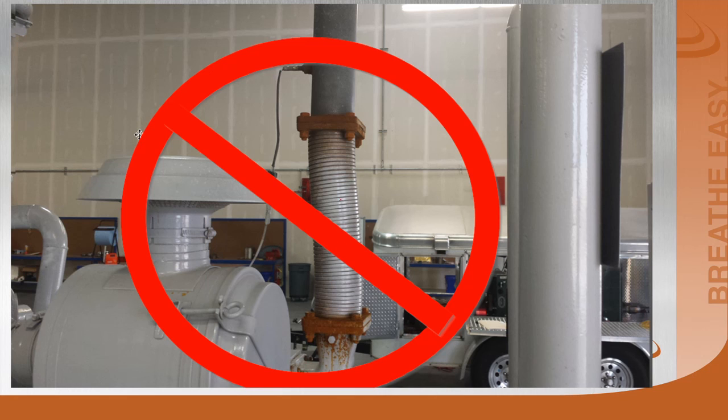Okay, galvanized flex pipe, that is a definite no. The galvanized poisons the catalyst, and then these leak real bad after a short period of time. They'll draw air in through all of these joints. The other bad thing about this picture is the oxygen sensor is located above the bellows. Sometimes you can't avoid it, but in most situations you always want to have this oxygen sensor located down here in this portion of the exhaust ahead of the bellows. That way if you develop a leak in the bellows, or in this case the flex pipe, you don't see that oxygen on the catalyst element and you don't overfuel the engine.